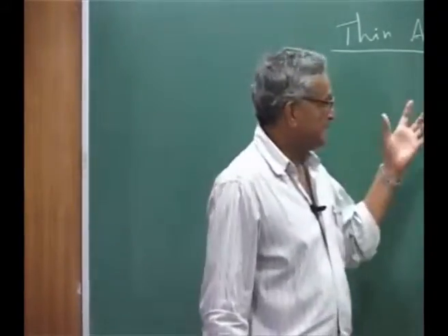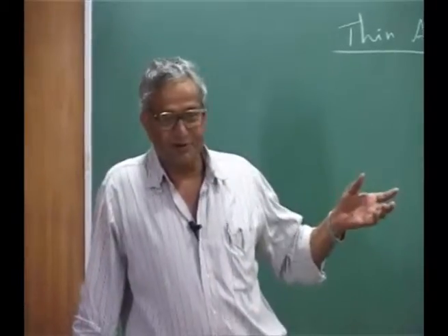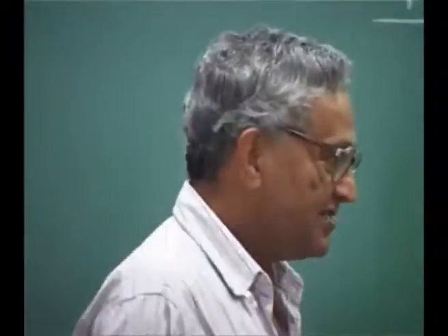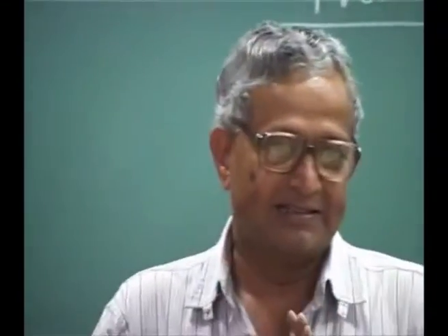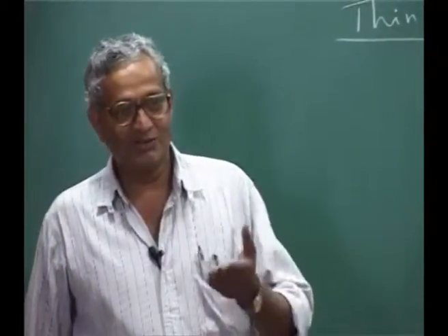Because this is one of the easiest problems in solving the potential flow equation. Supersonic flow is the easiest. The reason is because the flow is supersonic, any disturbance in the flow can go only at the speed of sound, because we made the approximation that the change in the local speed of sound is very small. Therefore, it goes with the A infinity only. As a result, the region of influence, okay, is slightly restricted, and we will see that particular part. Later you will understand, oh, that is why it is much easier to get the solution for a supersonic flow.